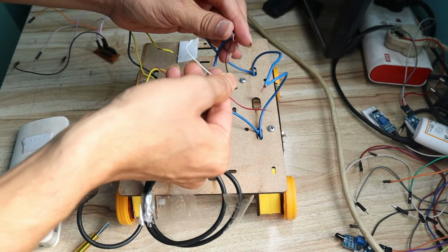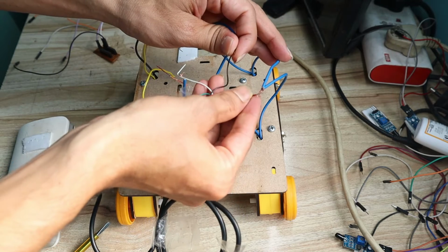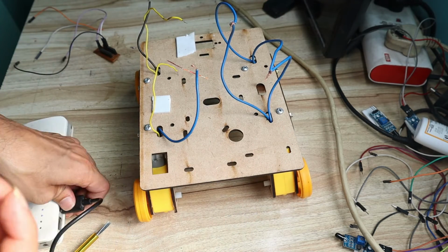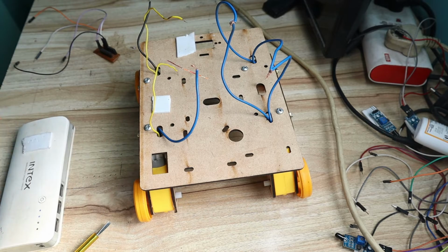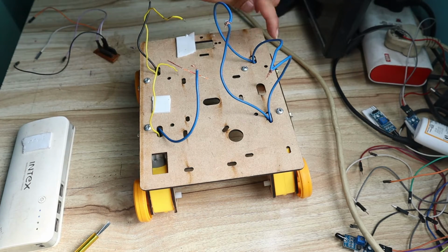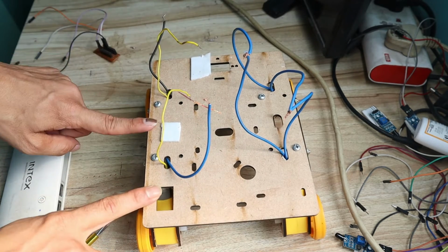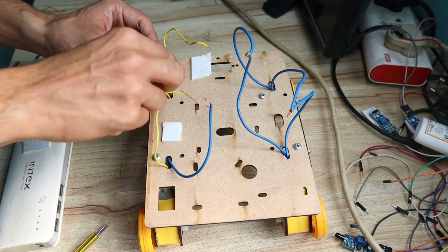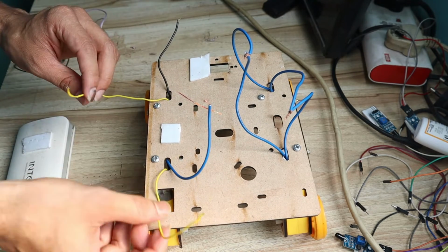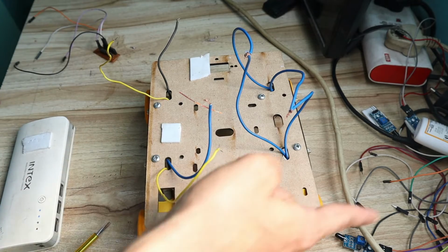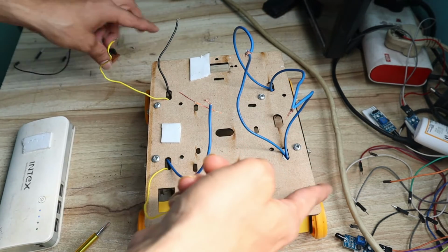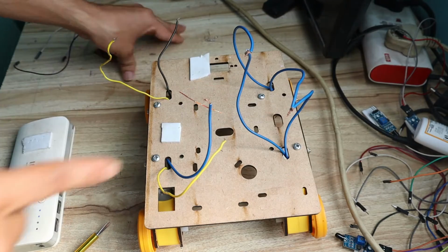So just connect the power supply. Okay, now I can see both my motors are rotating in the same direction. So this is the first step you have to do to find out the direction of the motor. With the same step you can find out the direction of these two motors. So again I will take random two pins from this motor. Now we need the negative direction, like this side direction we require. So the motor should rotate in anti-clockwise direction.